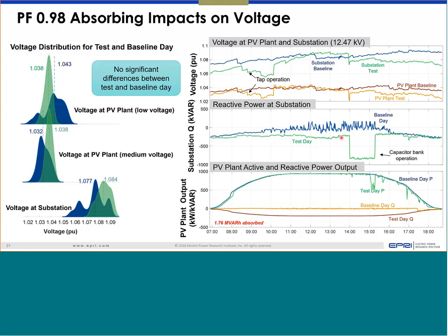Something happened in the middle of the day, a capacitor bank most likely, because we didn't see any cap operation. So that indicates it's a capacitor bank switching this large, almost 600 kVAR step capacitor, on and off. And voltage is very difficult to adjust at the plant and substation. The high voltage side is difficult because you have a lot of cap bank switching. So unless those are all coordinated, it is difficult to say which one is impacting what.